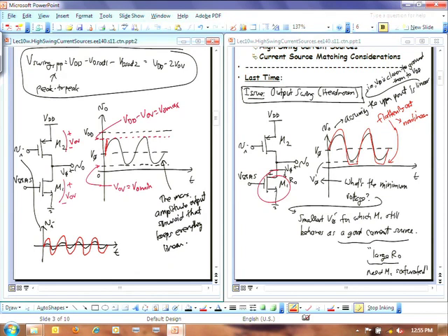And so instead of continuing to go with a fast slope, this curves out like this. And then it does this, that curves out, and so you get close to a square wave. Eventually, if you put in a large enough input signal, you'll get a square wave out of this thing. Okay? And so we want to avoid the red. In most analog circuits, you want to avoid this nonlinearity.